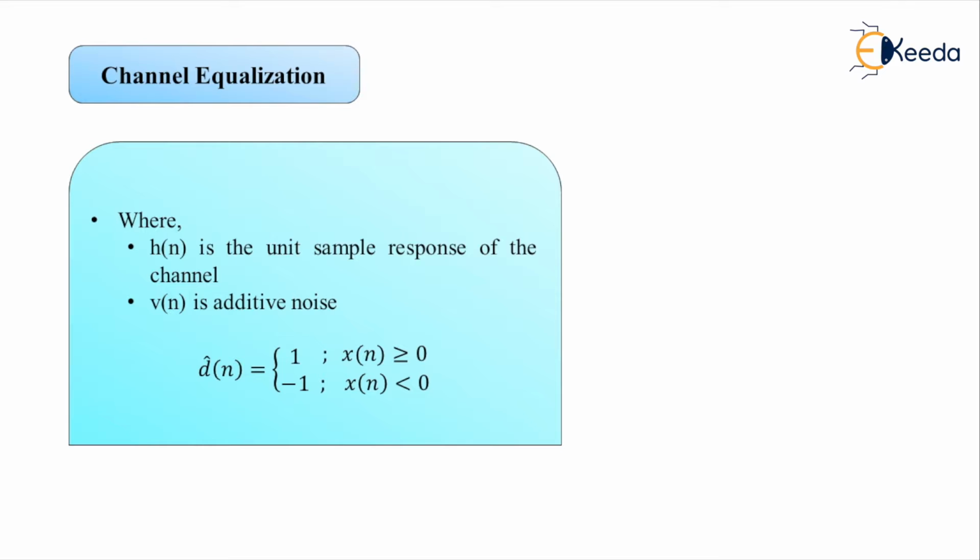Now in order to reduce the chances of making an error, we want the perfect signal to be decoded at the receiving end. The receiver will employ the equalizer. So this is our topic of interest, that is channel equalization. This is in order to reduce the effects of channel distortion. And since the precise characteristics of the channel are practically unknown, with possibly time varying constants, the equalizer is typically an adaptive filter. So this is the use of the adaptive filter design for the channel equalization purpose.